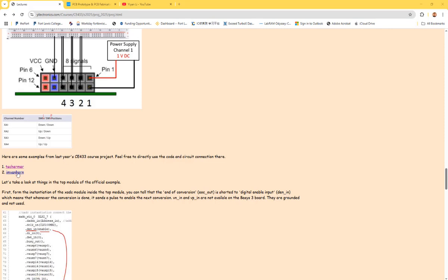And Ian and Mason saw the same issue, but eventually they gave up on the traditional method. What they did is they used the Arduino to write their own SPI logic instead of using the SPI.h header file. So they looked at the timing and wrote the timing in C by themselves. And it seems like that worked as well.